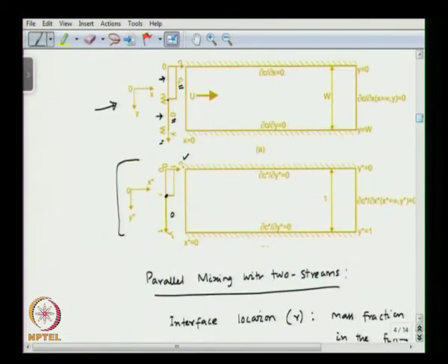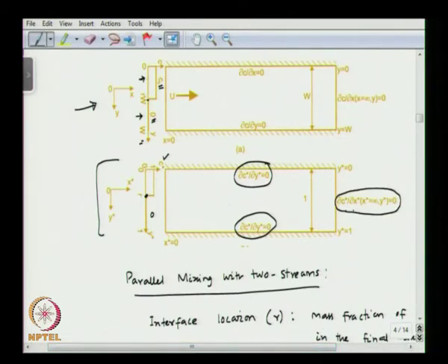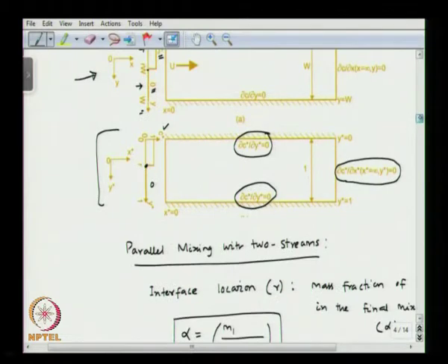So that is the boundary condition that we see here, del C star over del y star equal to 0 on the bottom wall as well as on the top wall, and this is the boundary condition at x equal to infinity, complete mixing boundary condition, okay. So we have boundary conditions on all 4 boundaries to solve the transport equation.